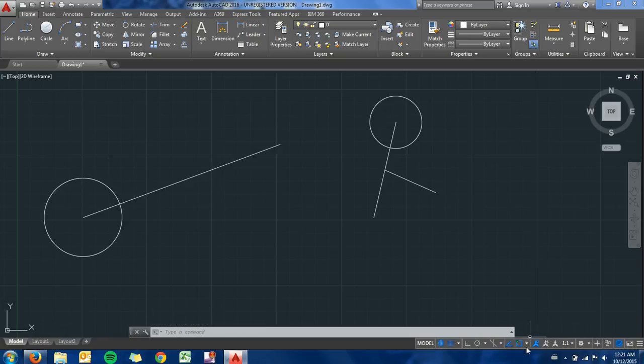So what I was talking about with the multiple ways to do things, if I just click on the object snap thing, you can see it's not blue anymore. I turned object snap off there, you can see in the command line, OSnap is off right now. There's a little hint for it. Along with typing commands, what I would typically prefer to do, you can see it says object snap, OSnap is F3. So if I go into the hotkey commands at the top of my keyboard and hit F3, you can see it says command OSnap on, and my little blue box has come back on. So I can either turn things on and off here, or I can just hit F3.